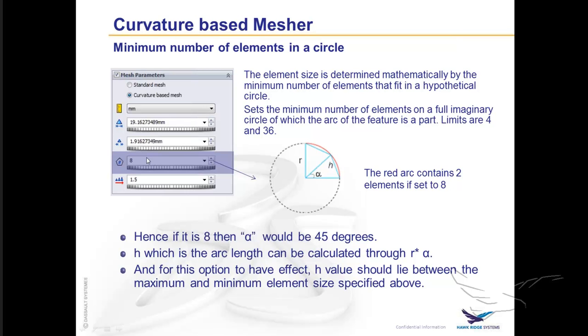So if you're finding that your highly curved areas are somewhat coarse, and you could use more mesh elements there, you can increase this to get a higher mesh density. And I'll illustrate that in a following model.